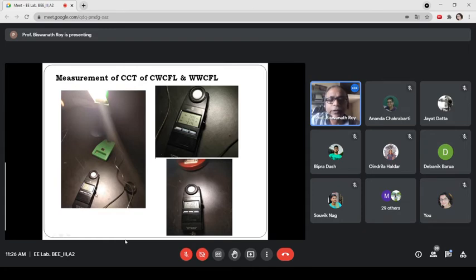When you switch on the instrument, the sensor is getting no light, no energy. Under this condition, the instrument sets zero automatically, because this is a very costly, very sophisticated instrument. It sets zero using the internal algorithm. So zero is visible here. Zero for what? Zero for illuminance.